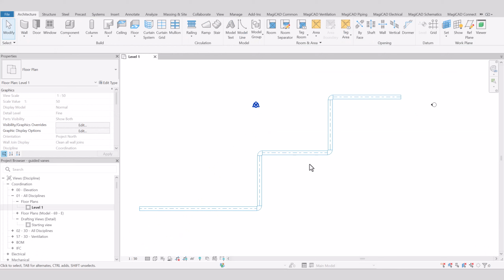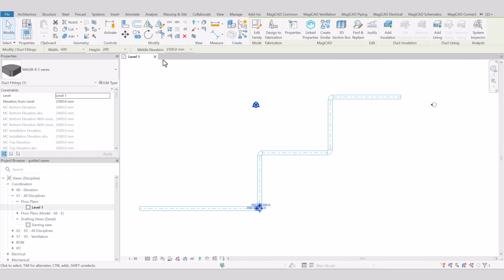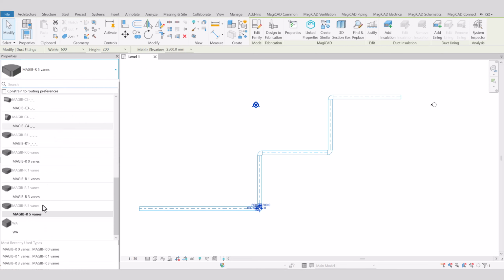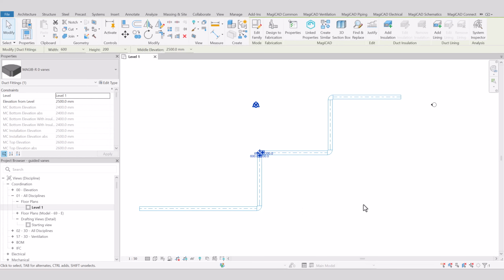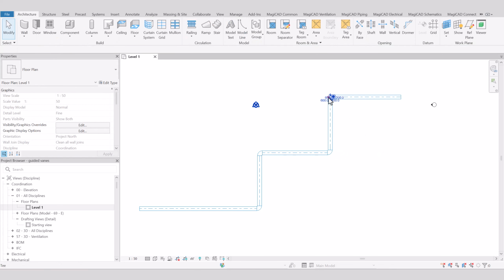Pressure drop calculations for duct bends with guide vanes has been improved. If there are more than 3 guide vanes in a bend, warning is shown in the report due to lacking measurement data for such bends, and calculation uses data from the case of 3 guide vanes. So I have different bends. For example, this one has 5 vanes. This one has 0 vanes, 3 and 5 accordingly.